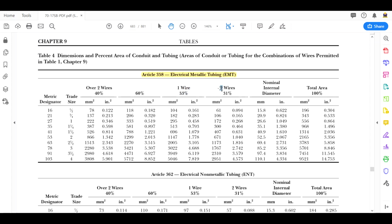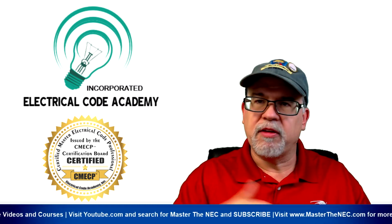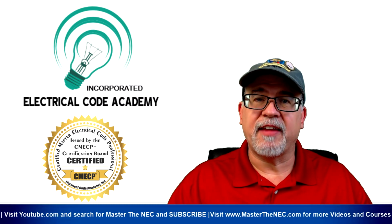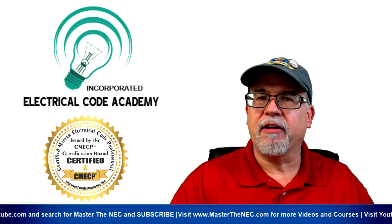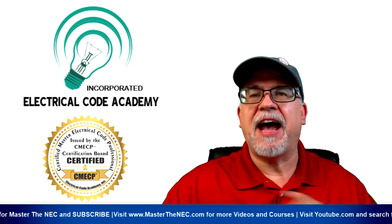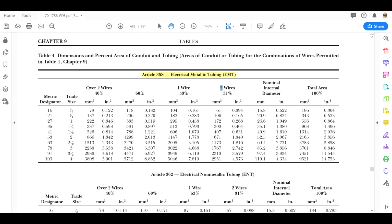Here's your 2 wires that can't exceed 31% of this total area over here. So these are percentages of this total area. Now, a couple things to remember. If you ever get on an exam all these values, all these conductors and everything, and at the end of the question all it says is, give me the total area of a 2-inch EMT, then all of those values on the conductors mean nothing, because all they're asking you for is the total area. And if that's the case, then this is the total area.